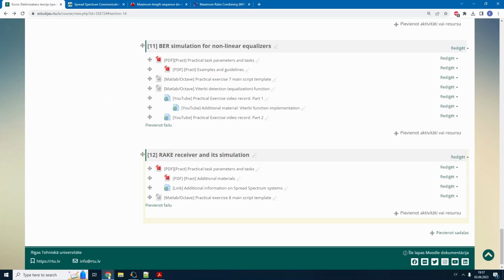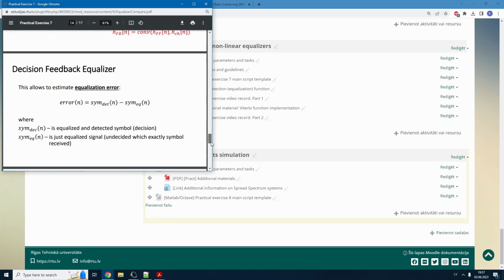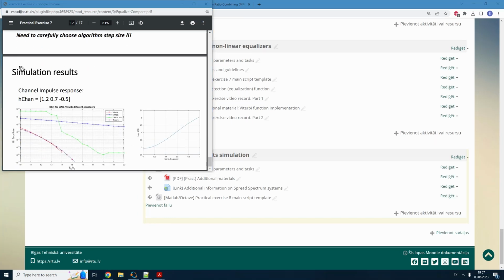This is unlike the channel we had in practical exercise 7. Accordingly, here you may realize that we talked about some channel that I called very bad. Now you can see why this channel is very bad, because normally our signal lies within here, and as you can see this channel doesn't amplify our useful signal much, but it significantly amplifies the noise. So the noise is getting stronger and stronger the higher its frequency, but the signal is not getting as strong as the noise. So this channel specifically amplifies noise for our signal. And since we didn't use any filtering in our practical exercise, this actually had a big effect. But even if we would use filtering, it would still amplify the noise and the effect of filtering would be smaller.